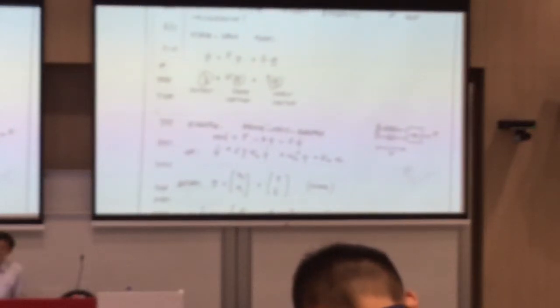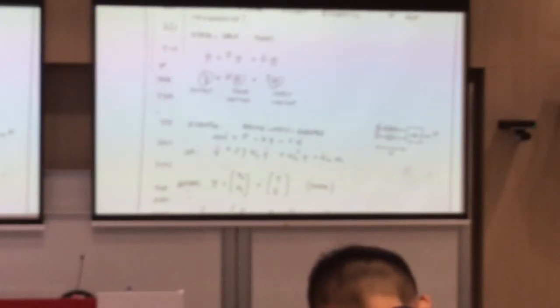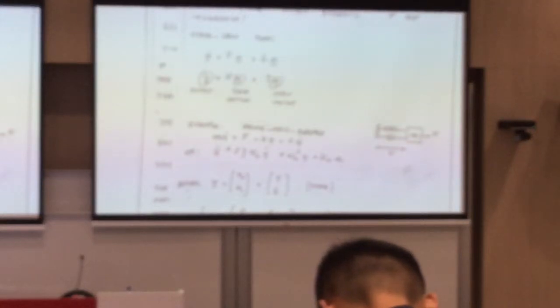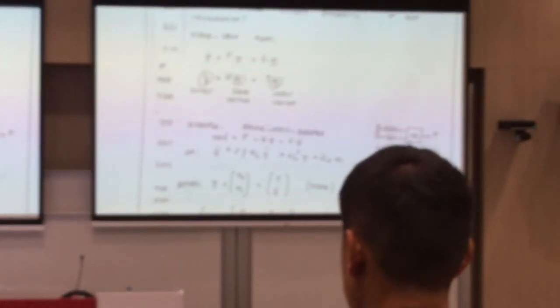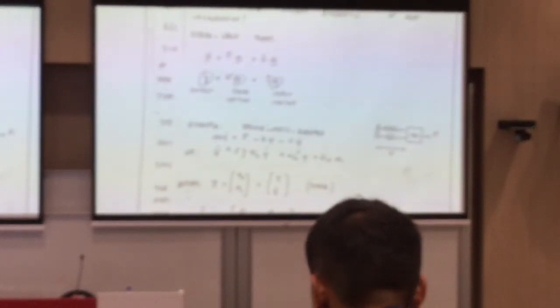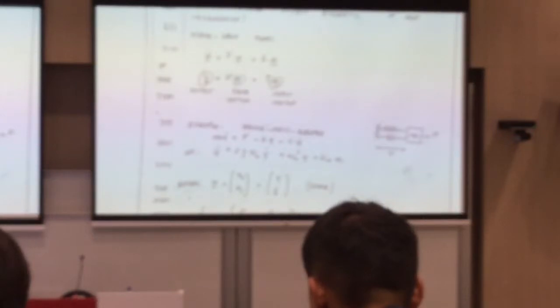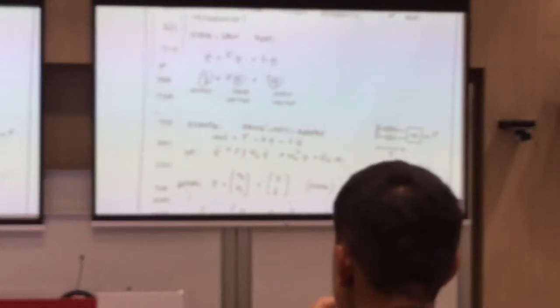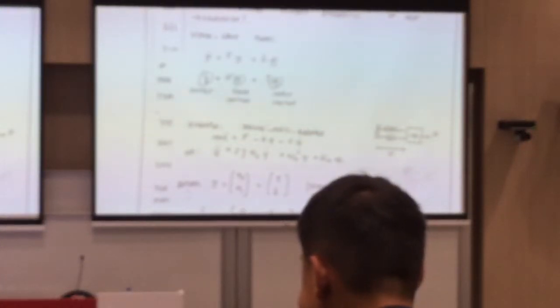And the other one, which is something we are doing now, is the modern control. Basically, they convert the high order differential equation to state space. And what is state space? The tricky part is they convert your high order differential equation into a higher rank of equations, but each equation is only first order. If you notice your state space equation, if you talk about differentiation, it is always first order, plus some constants.